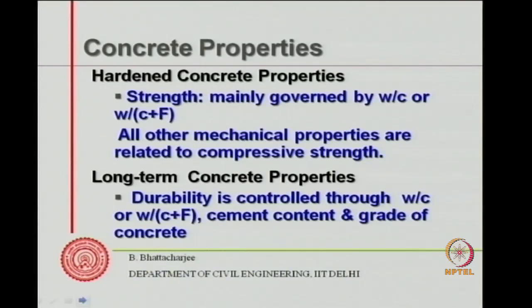And water cement ratio governs this. Why does water cement ratio govern this? Because water cement ratio controls the porosity and pore sizes of cement paste, as we have seen. Even in concrete, the same thing happens. We have seen in the microstructure development of cement paste that it is the water to cement ratio which governs the capillary porosity. Higher water cement ratio means more capillary pores. Therefore, strength of the concrete, which is a function of the porosity and pore sizes, is governed by water cement ratio.